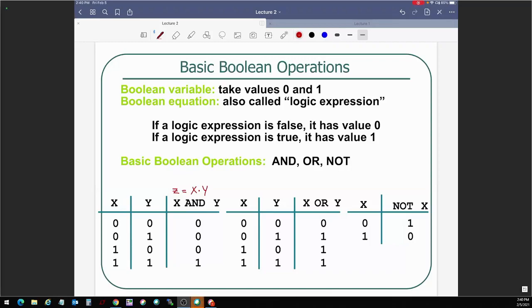Isn't convolution only for analog things anyway? No. So there is continuous convolution. There is also discrete convolution. So you could have convolution for both continuous things and discrete things. It's not just for one thing, but you use convolution to find the output of a linear time invariant system when you are given the impulse response and the input for that system, right? So it's meant for a different purpose.